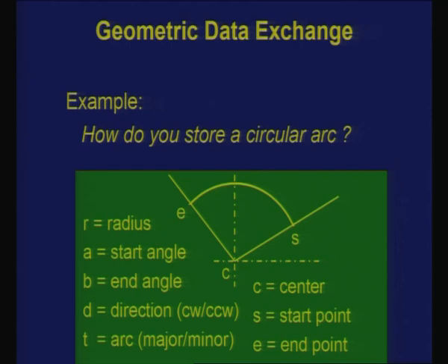If I just take an example, I referred to this example earlier also, suppose I want to store a circular arc. Here is a segment of an arc, S indicates the starting point of the arc, E indicates the end point of the arc, C is the center point of the arc. Now, when I store this particular arc in my native format or as a part of a software, what are the values which should be stored?